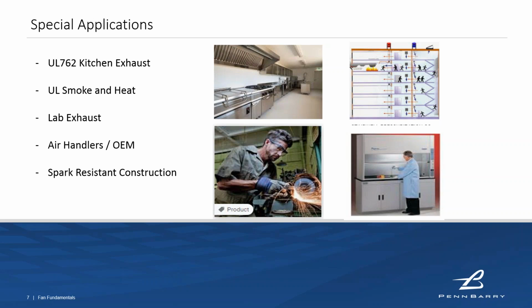That's where you're going to see applications with known combustible material, be it gaseous or dust. AMCA B is going to say that I need to have a non-ferrous wheel, almost always aluminum, along with some rub plates. AMCA C is really just a normal fan, but I put some aluminum or some brass around high contact probability areas.